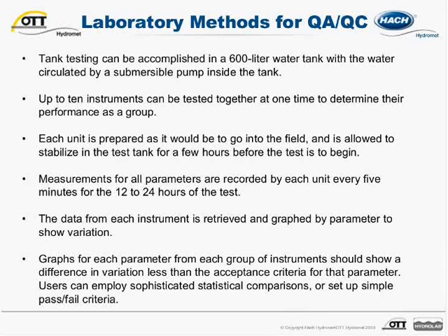For a basic tank test setup, put a submersible circulating pump at the bottom of a large tank, like the one seen in the photo in the previous slide, and fill it with water. A large garbage can often works well and is easy to find at a local hardware store. In this type of setup, 10 sondes is usually the maximum number that can be tested together as a group.